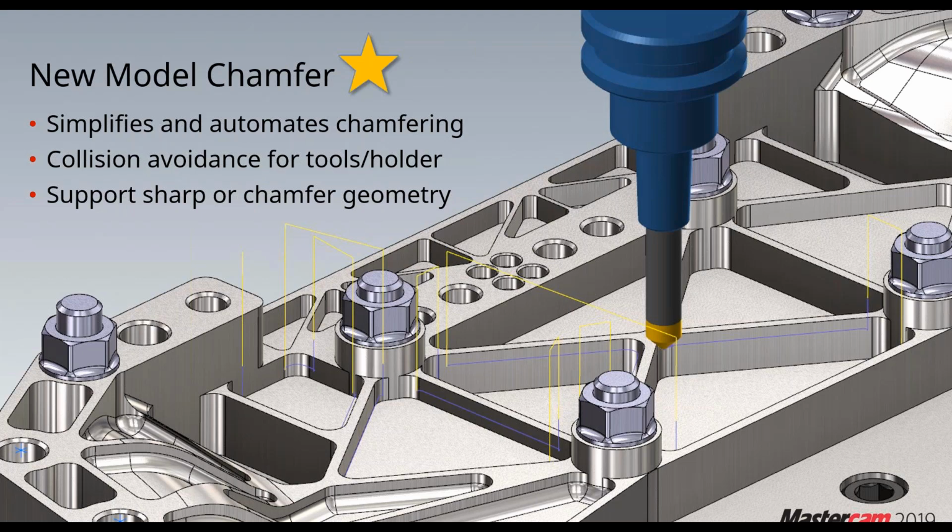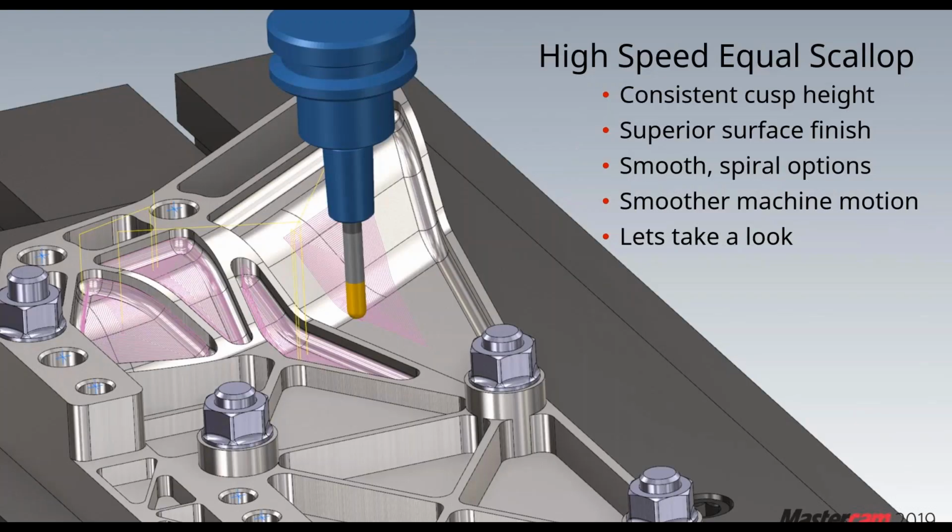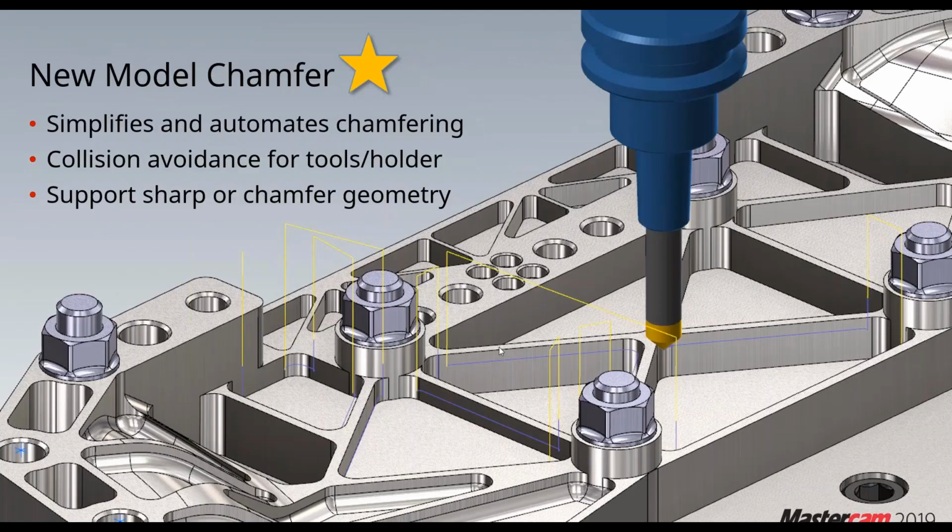So chamfering like a 3D profile, which is difficult in and of itself because the back of the tool is going to want to wash away the material the steeper it gets. But just be mindful of that. So if it's not calculating or it yells at you, you have to make sure that it's flat geometry.